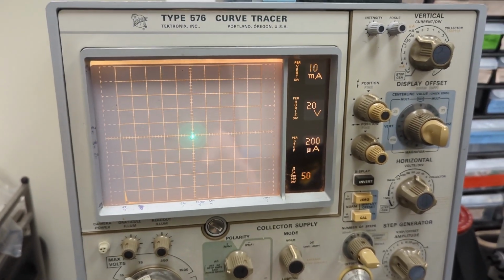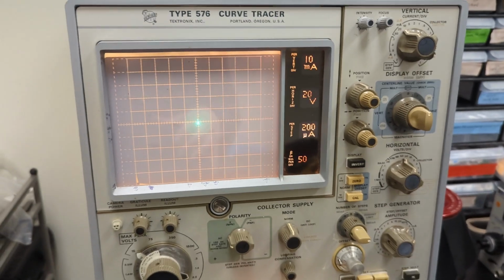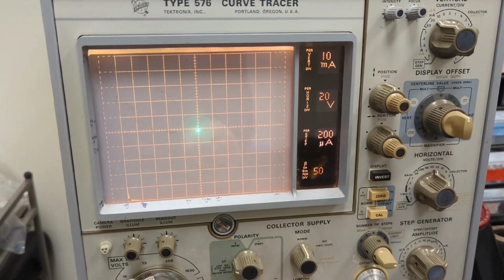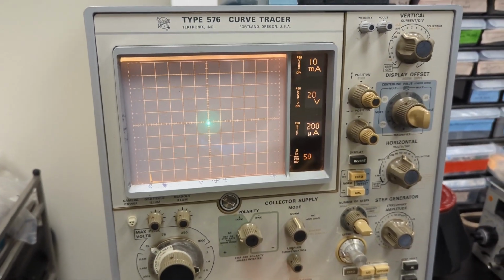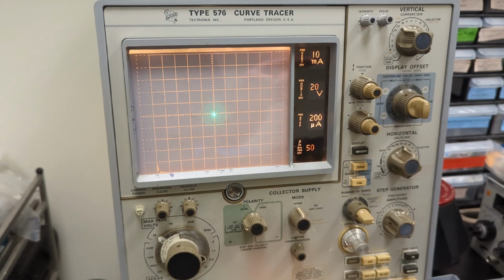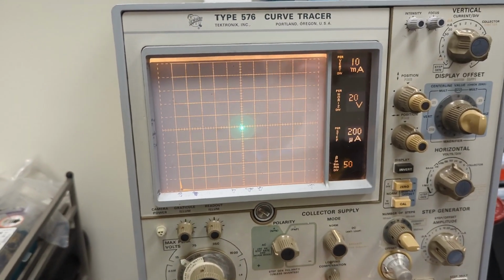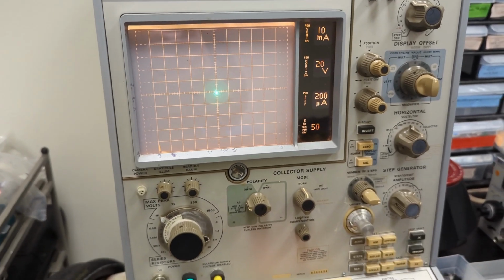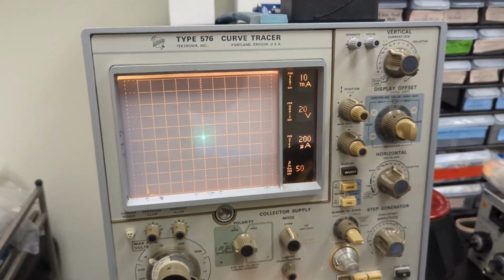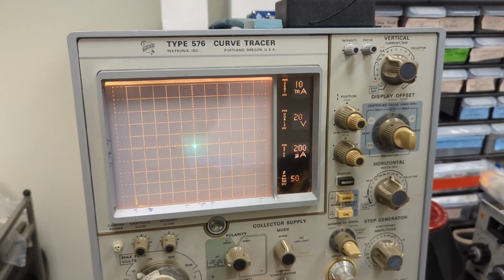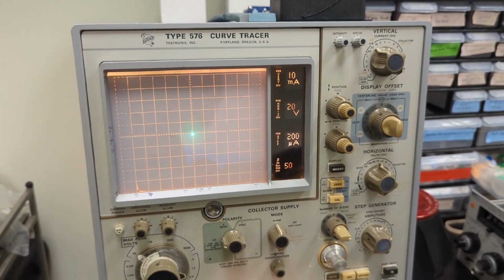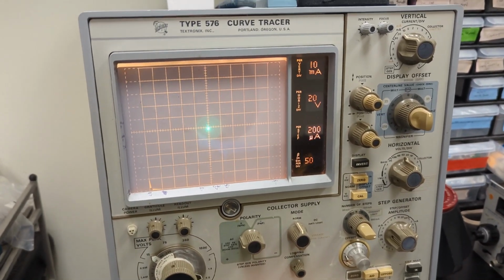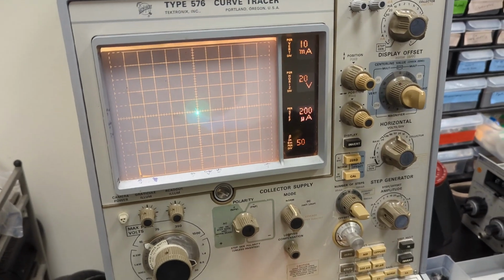It was measuring funky in circuit, which is another thing. I think it was like 1.7 volts with the diode test function. Although it could have just been the surrounding circuitry, I have to measure it out of circuit to see. Yeah, I think this guy was the culprit. But let me see if I have anything similar. I don't think I have a 9-volt Zener diode, but I'll check. Let me see what I can dig up, and we'll go from there.